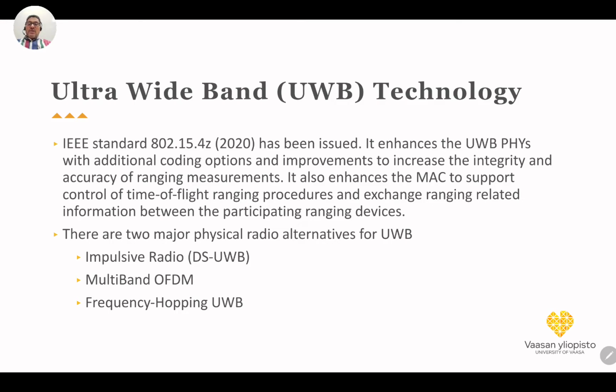We have mainly three standards or alternatives for the physical layer: the impulsive radio, called direct sequence ultra wideband, the multi-band OFDM, and the frequency hopping ultra wideband.